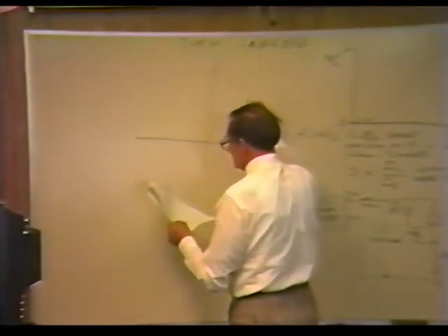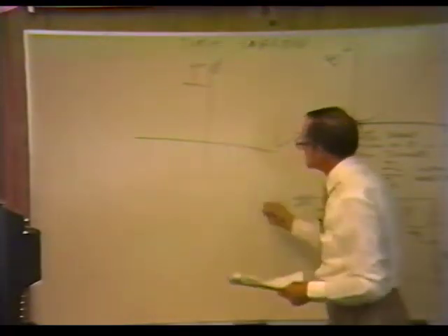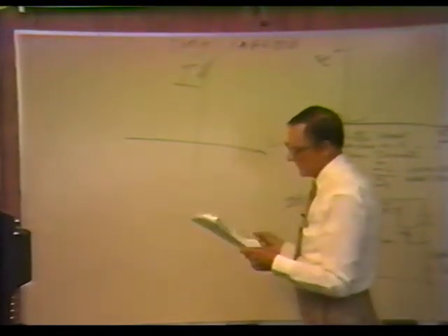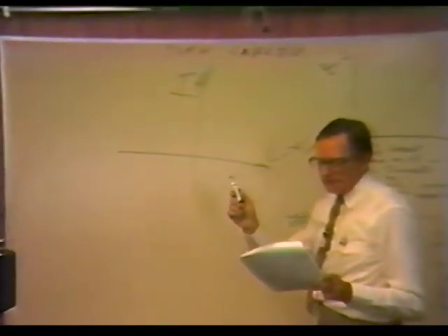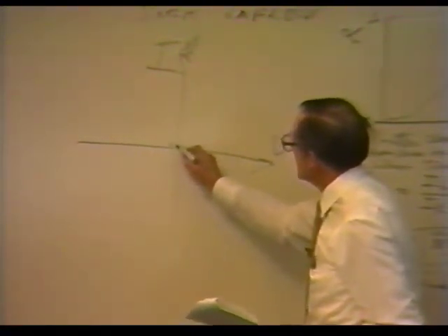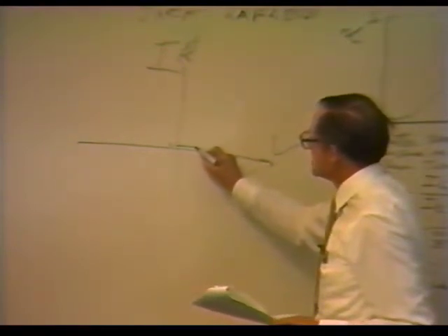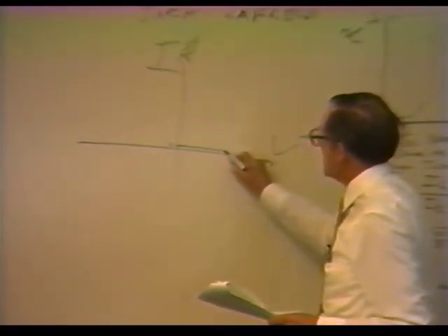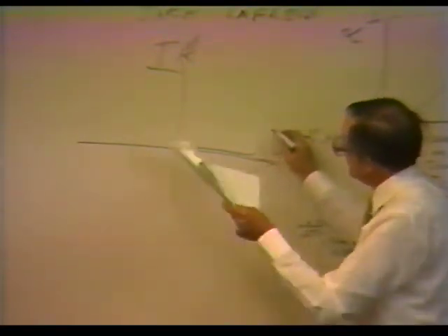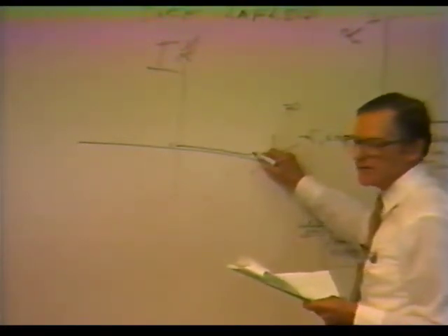on a current voltage curve what happens. We have voltage in this direction. This is current in this direction. In the forward blocking condition now, I have very little current flowing as I push higher and higher on the anode voltage, and I get out here to a point, and we use 30 volts as an example, where we're passing now the breakdown voltage.